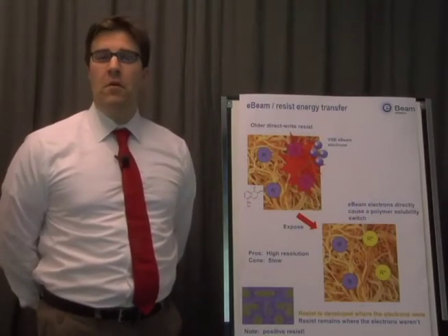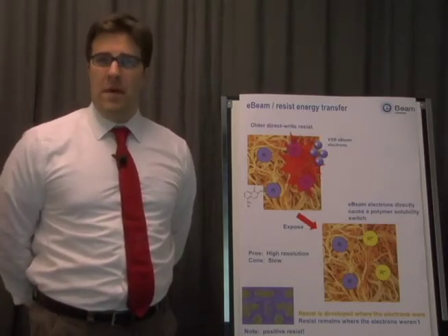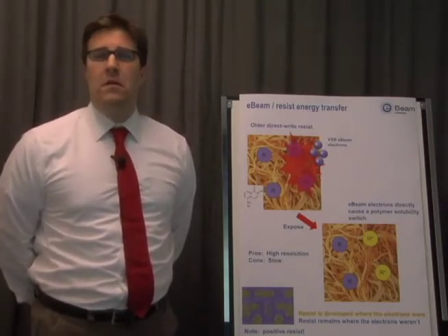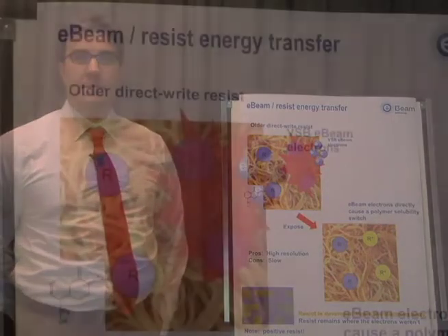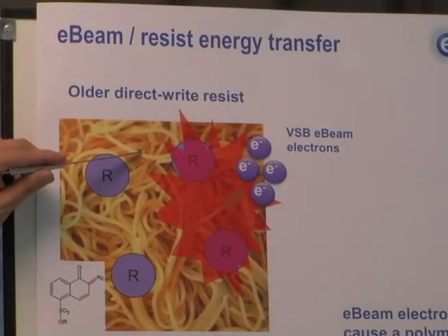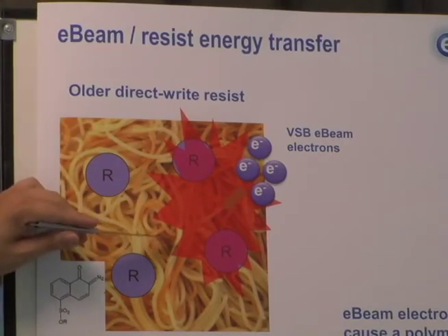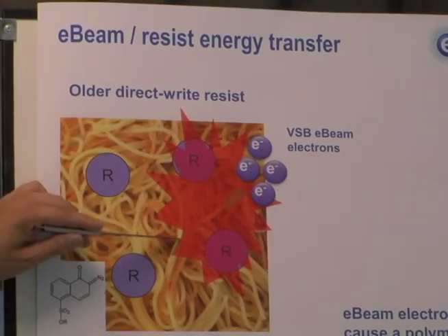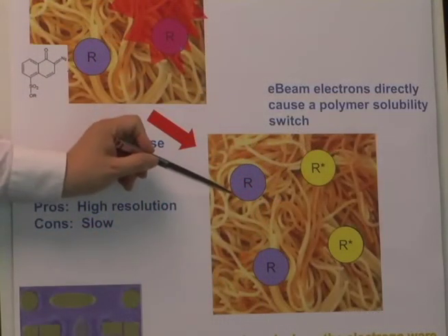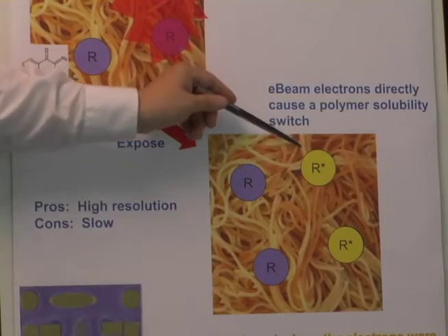So to start with, we'll go back a little bit in history and talk about the simplest photoresist possible, PMMA. Now, PMMA is really nothing but a long, simple hydrocarbon polymer chain that's insoluble in an aqueous solution. So the secondary electron capture events will result essentially in a breaking of carbon-carbon bonds in these long chains. Such reactions then, electron by electron, will create shorter and shorter polymers, and as a result, they will be increasingly more soluble in the aqueous solution. So in this picture, we represent the bond scission from R to R star as they absorb the electronic energy during the electron beam write itself.